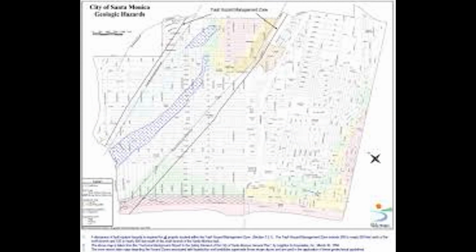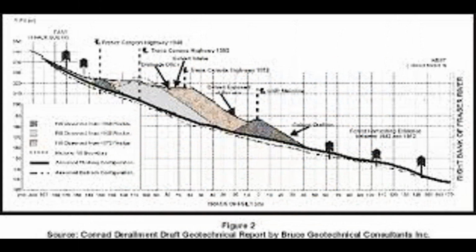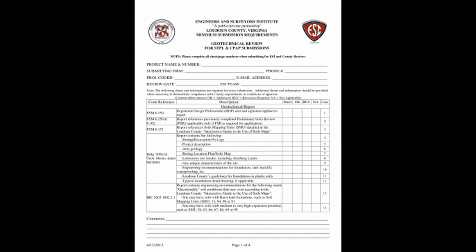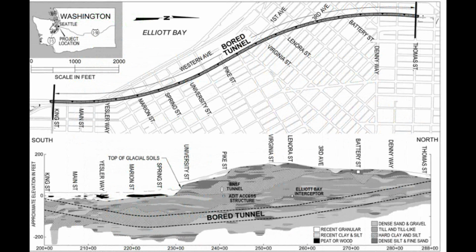This is commonly the case on large projects or projects containing complex or difficult geotechnical problems, where alignment and/or grade changes may be appropriate based on geotechnical recommendations. The development of a final geotechnical report will not normally be completed until design has progressed to the point where specific recommendations can be made for all the geotechnical aspects of the work. Final alignment, grade, and geometry will usually have been selected prior to issuance of the final geotechnical report.